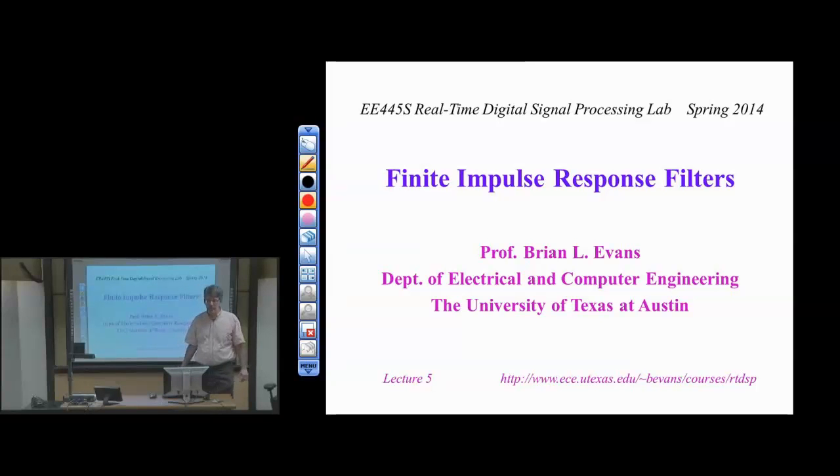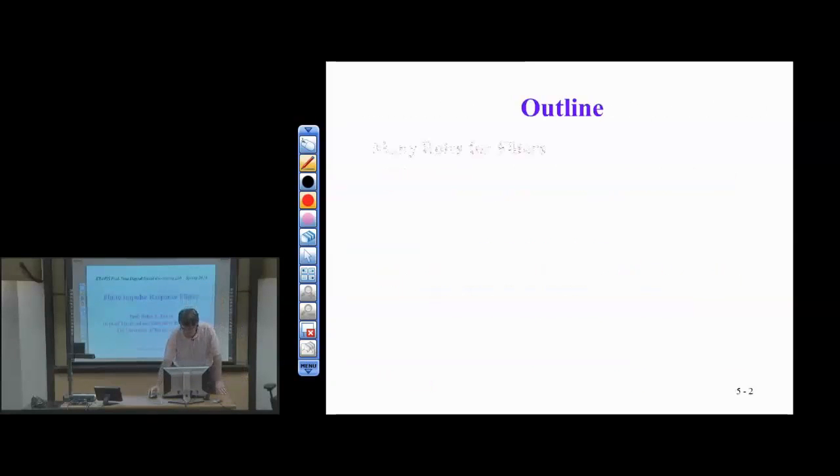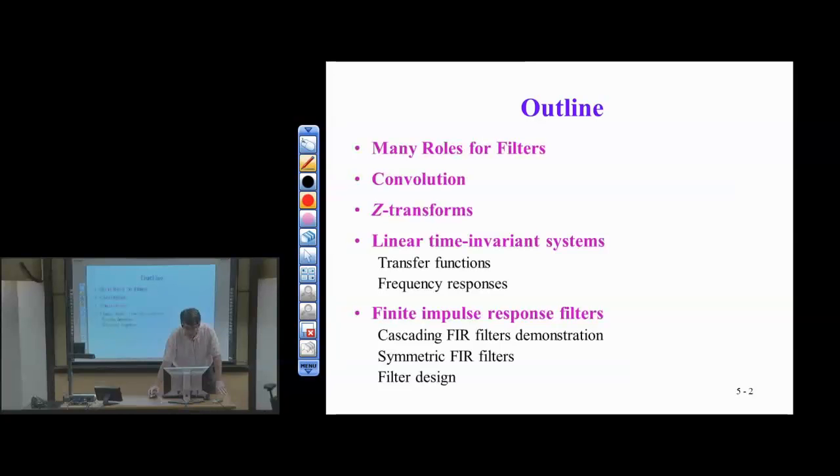Lecture 5 is on finite impulse response filters. So far we've covered quite a few things. We've covered many roles for filters: spectral estimation, spectral analysis, and spectral shaping. We talked about convolution. This is how filters work in the time domain. The output in the time domain is the convolution of the input signal in the time domain and the impulse